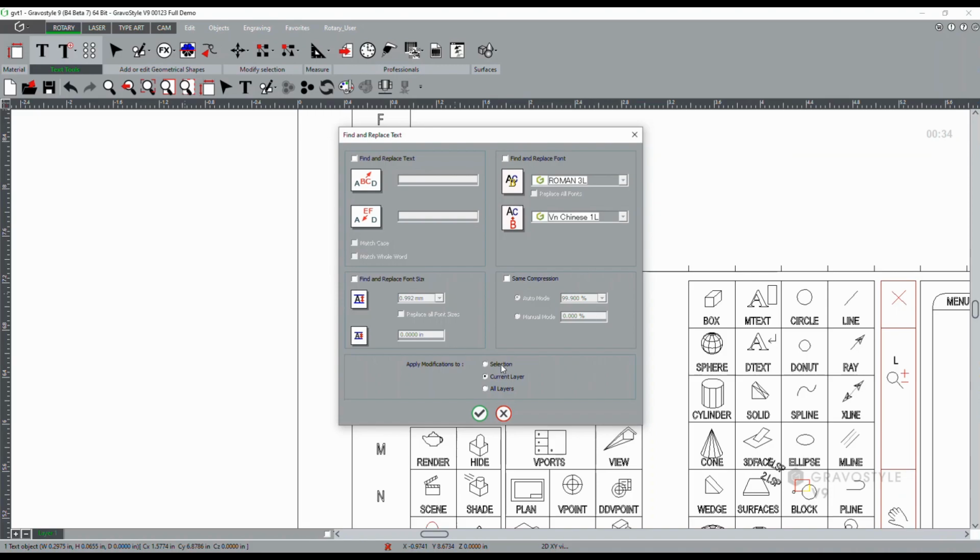I can make these choices based on either the item selected, the current layer, or all layers. If I have brought the drawing in and retained individual layers, for example, for text versus graphic logos versus the grid frame that everything is drawn on. But in this case, I'm working with the current layer, and because I had it merge those, everything is on that current layer.